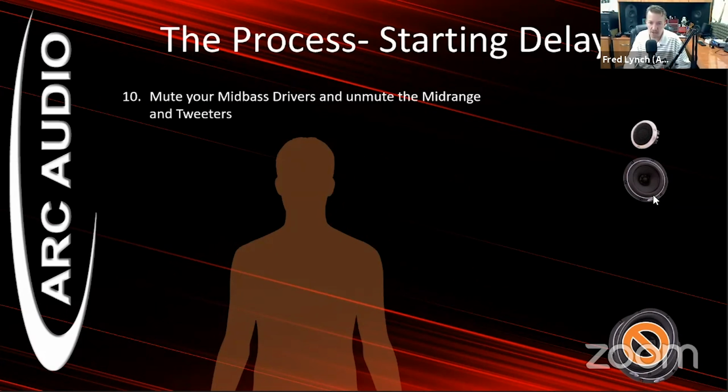Now, in this case, the tweeters are farther away from the listener than the mid-range. So we're going to want to delay the information on the mid-range so that it sounds like one physical pulse, not two. Right now, if you listen to it, it would sound kind of like da-da, really quick. What we want is all the mid-ranges and the tweeters sounding like one pulse coming from the vehicle. So it'd be like da, even though at this point we have 4 speakers playing.